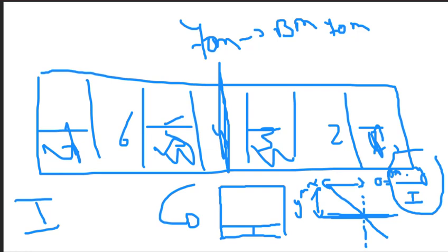If you have your bending moment and your I, you can easily calculate it as well for your double bottom structure, meaning your lower plate as well as your tank top. You just have to vary the distance and then you have your values. The bending moment max we calculated last week and it was given as 52,500 ton meter.